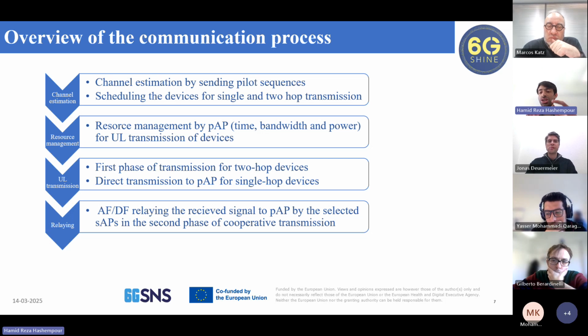And by changing the CSIs, we have to rearrange all these precoders for each device. So the overall overhead of the RIS, especially in the case that we have a large number of elements, which is relevant for the case of, for example, FR2 or millimeter wave, where we have thousands of elements, is a very highly loaded problem to optimize jointly the precoders and the powers.